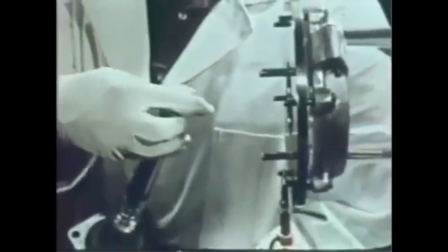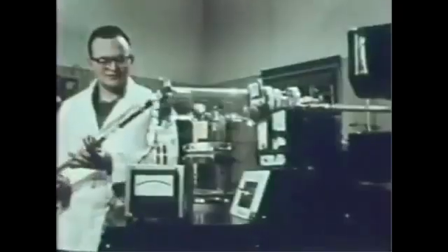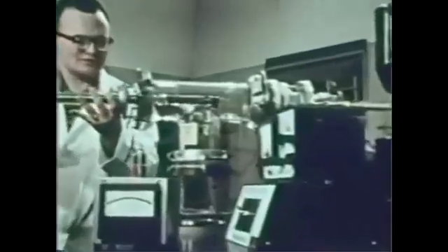As an example of our research in IC technology, we're studying new ways for getting impurities into semiconductors. Normally, this is done by diffusion. We do the same thing by ion implantation. This machine takes individual ions and accelerates them, ramming them into semiconductor material much the same as you would shoot a bullet into a bale of hay. Right now, this is a much more expensive process than diffusion, but it's a different technique. Here we're not interested so much in developing the technique as we are in learning the fundamentals. How heavily can you dope materials, and what kinds of materials can you dope this way?